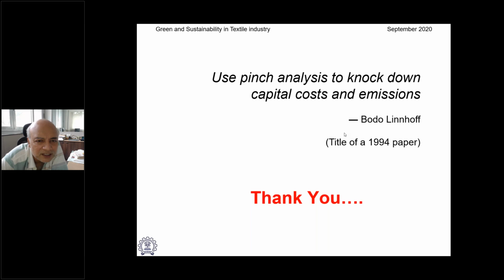One question has been asked by Balaji. He said, in the optimization, is it compulsory for the pinch temperature to be 9 to 10 degrees? Okay, no. Again, it depends on the process and application. It can be as low as 4 to 5 degrees. That is the temperature difference, not the pinch temperature. Pinch temperature is the temperature at which the minimum delta T occurs.